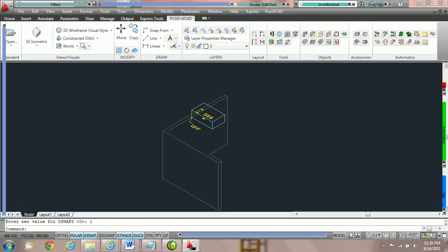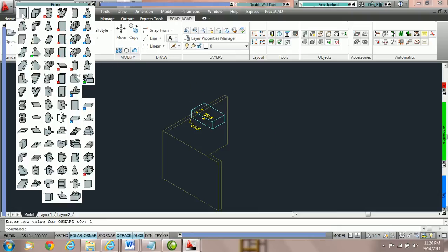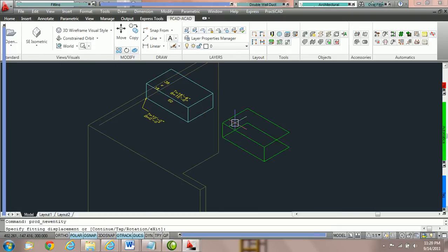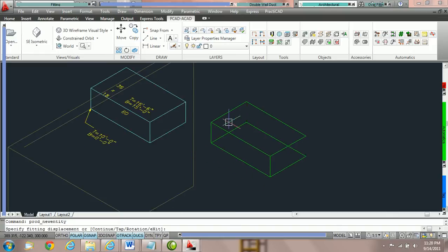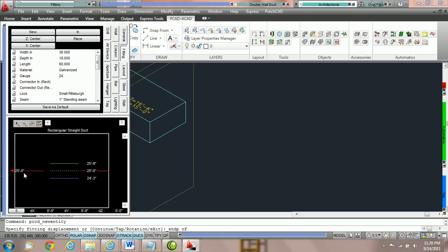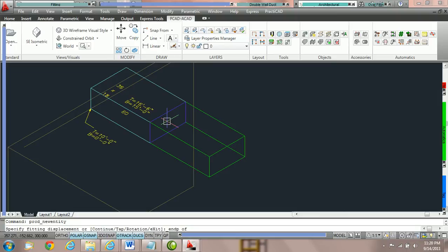And we've set Replace Z on, and what this means now is if we go to grab a piece of duct, normally in isometric view, if I isolated an endpoint and I brought this duct over to meet this fitting, we should see the endpoint node, if our snaps are turned on, right there. However, here we do not. And the reason why is our current elevation is at 25 foot. This duct, its bottom is at 15 foot.